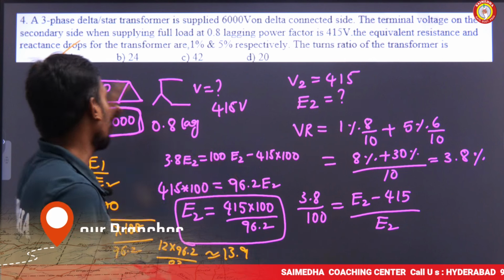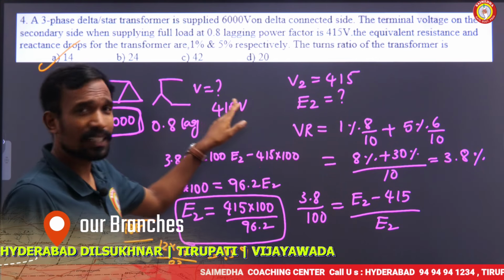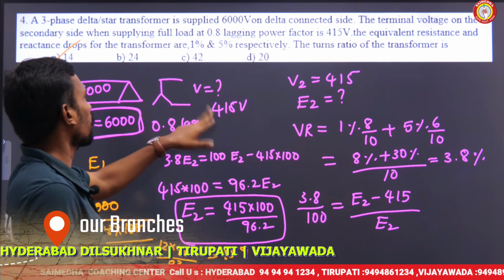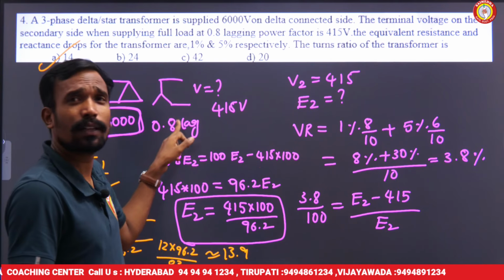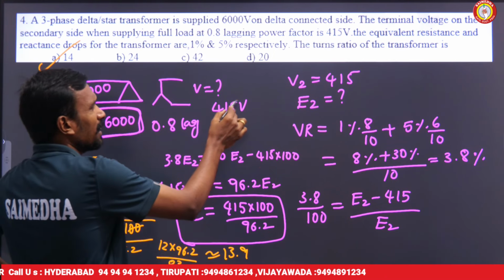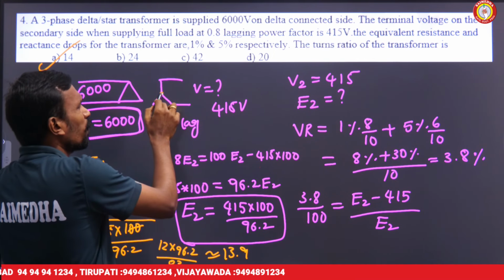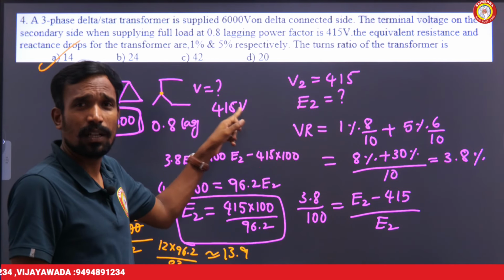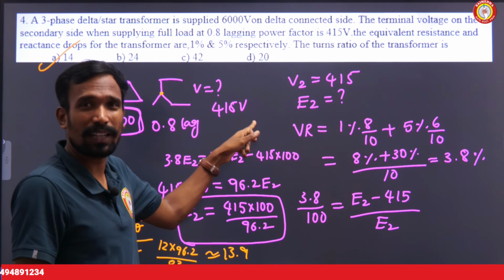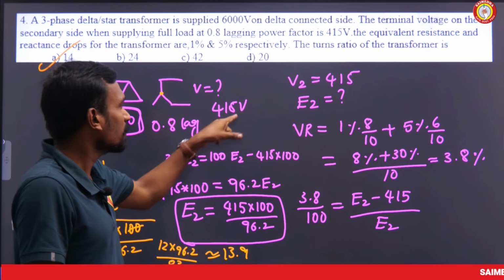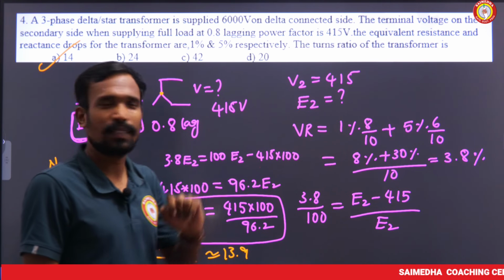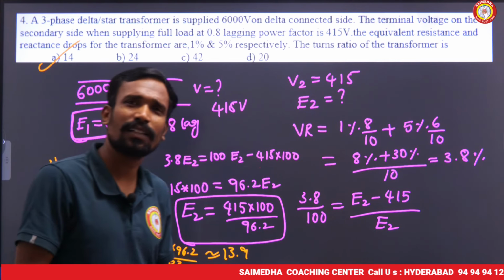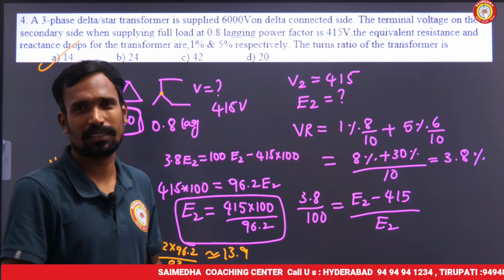So what have they given? The primary line voltage and the secondary line voltage. Of course, we can calculate from this also, but this is at a particular load. Don't simply take this line voltage and find the phase voltage, because this is a load voltage, not the EMF. That's why we need to calculate the EMF. Then in the voltage regulation, what we get are the phase voltages.